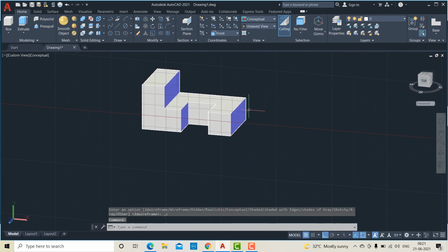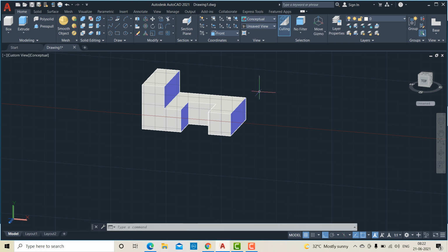So this is how you have to draw the given constructive solid geometry. I started from the front view, drew the shape, extruded it, and then drew a rectangle. Initially I made a mistake, drawing it as 20 by 25 instead of 25 by 20. I rectified that mistake at the end. Then we used the subtract action to remove the unwanted portion from the drawn geometry. Also practice the sum. Thank you.